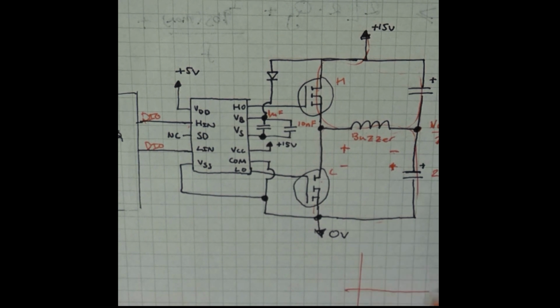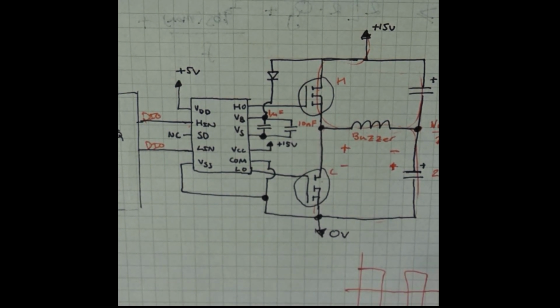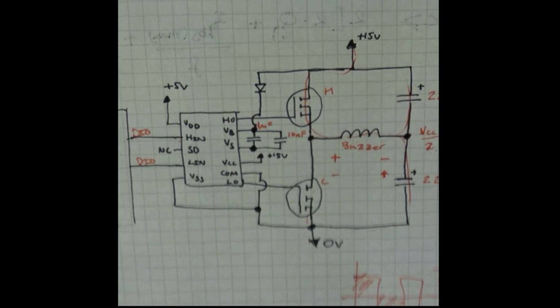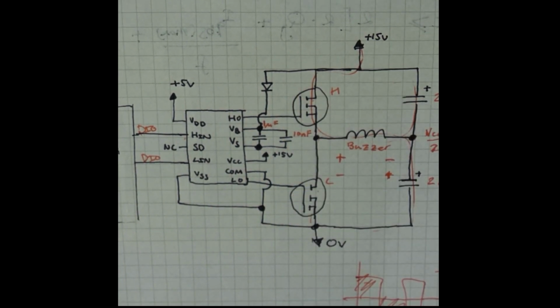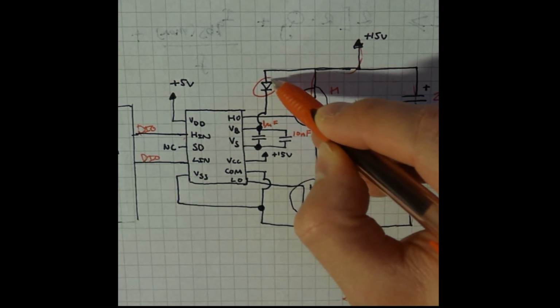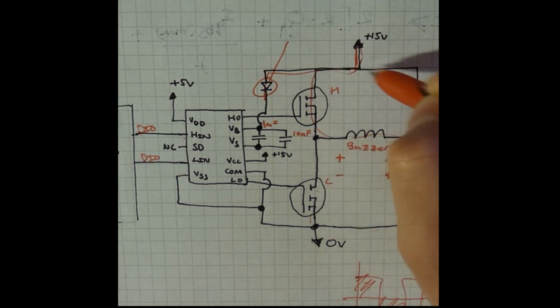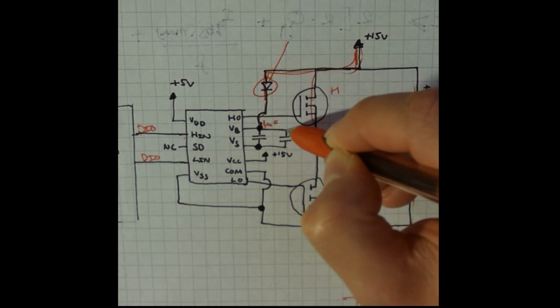So we're doing something like this. This is beneficial for a Tesla coil because the average of this and the average of that, your RMS, is essentially 0, which means that ideally you have less switching losses and less power dissipated in these two switches, which is also obviously very good. There's my bootstrap diode there. As I said before, it's charging these caps up.